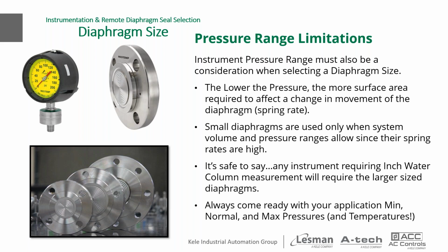But a lot of customers basically find it by looking at other pressures. For example, they may have another transmitter downstream that's reacting properly, and then when they see a sluggish response on the transmitter seal that they've installed, that's generally how they might know. In other words, there tends to be a little confidence crisis in what's being reported by the instrument. So yeah, not working at all would be the worst case scenario. Being sluggish or slow to respond would be another one.